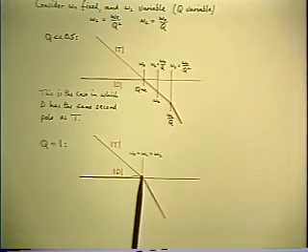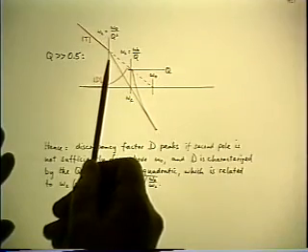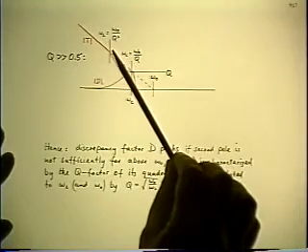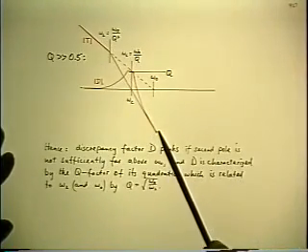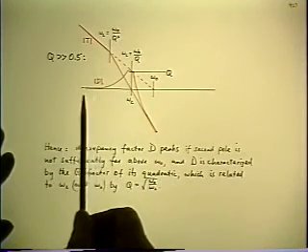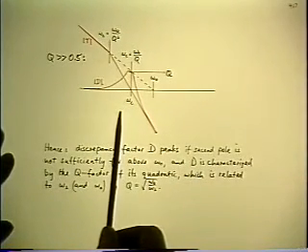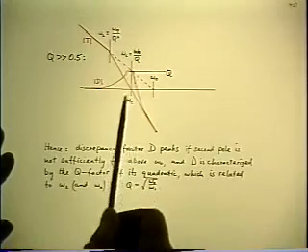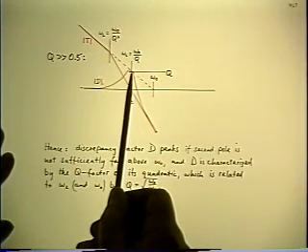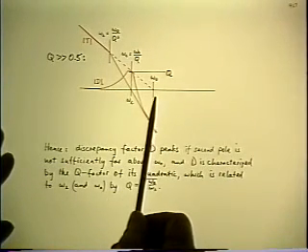Well, what happens if you go to an even bigger Q, which is what happens if the second pole in T comes in even before the original crossover? So now you're crossing over on a double slope. And now the quadratic, representing the closed loop response D, peaks up significantly for a high Q. And the geometry is such that at the corner frequency of the quadratic, the closed loop response actually goes through the point that lies on the asymptote of the original slope.